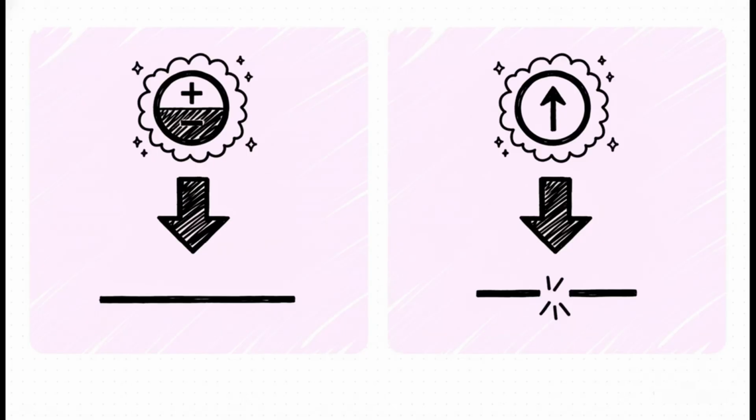Now that step about deactivating sources is absolutely critical, so let's zoom in on that for a second. What does that actually mean? Well, for an ideal voltage source, making its voltage 0 is the same as replacing it with a perfect wire, a short circuit. And for an ideal current source, making its current 0 is like cutting the wire completely, an open circuit. You have to get this part right or your Thevenin will be way off.